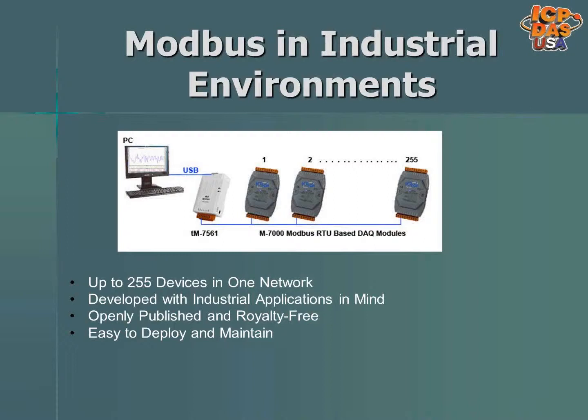All Modbus commands contain checking information that ensures commands arrived intact. The basic Modbus commands can instruct an RTU to change a value in one of its registers, control or read an I/O port, as well as command a device to send back one or more values contained in its registers.